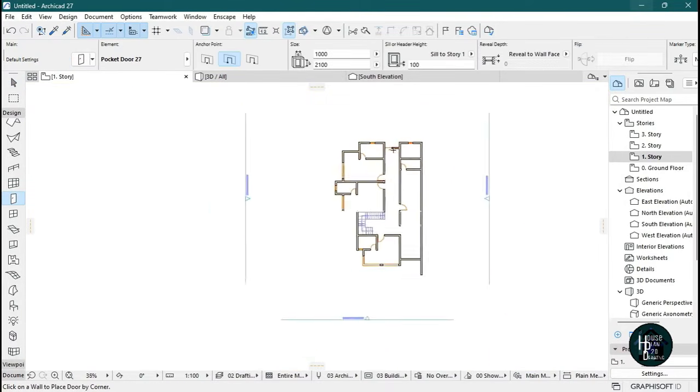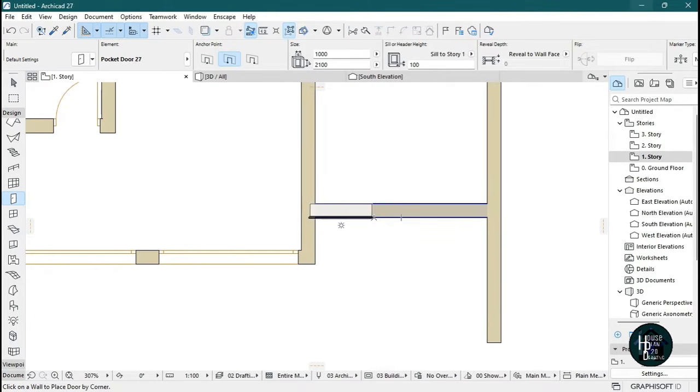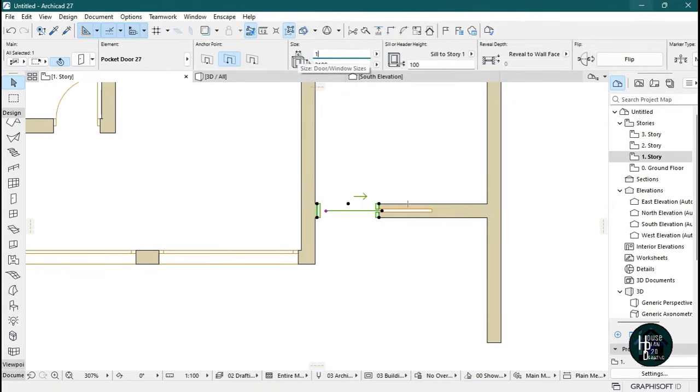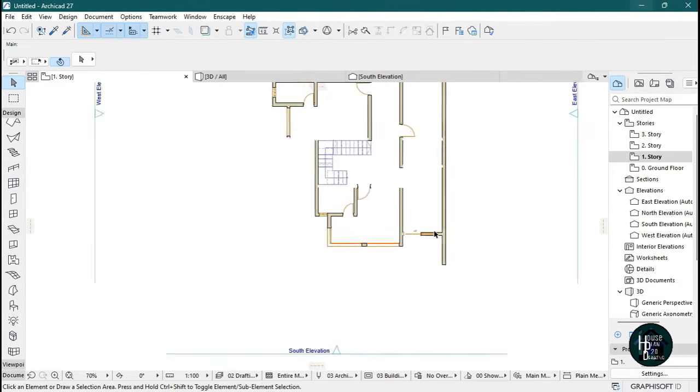You also need this particular door to be somewhere around here too, for the entrance to the veranda. So click, and let's open it like this. This can be bigger because it has enough block space. So click on the door, and let's give a distance of, let me say, 1 2. Then click enter. Click on this node here, and let's bring it back. Make sure you're selecting drag and select this side here. So we have something like this.